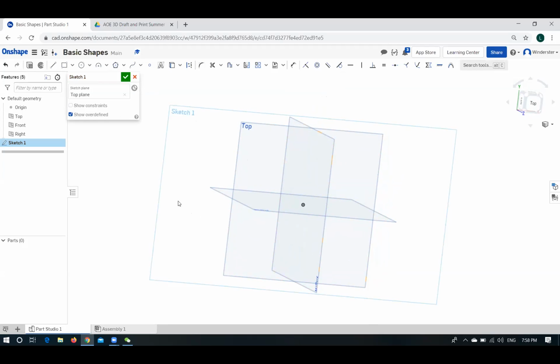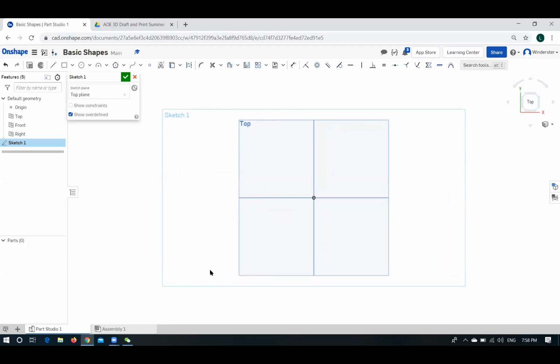Okay? When I press on the blue thing, nothing happens. Doesn't matter. Okay. Once you click on the drawing plane, that part shouldn't be blue anymore, right? It says top plane in that field. Okay, good. So right click onto sketch 1 plane. A menu shows up. Hit view normal to sketch plane. We got that far? Yeah.